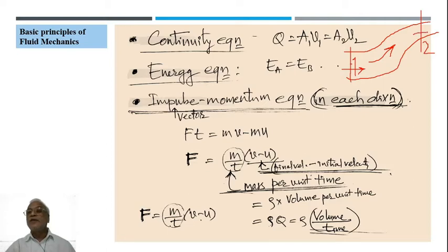Similarly, over here, if you have cross-sectional area as A2 and velocity as V2, then the discharge cannot disappear or cannot get added, right? That's why this equation holds good. A1 V1 is equal to A2 V2. Unit wise, cross-sectional area is in meter square, whereas velocity is in meter per second, so it will come as meter cube per second as the discharge.